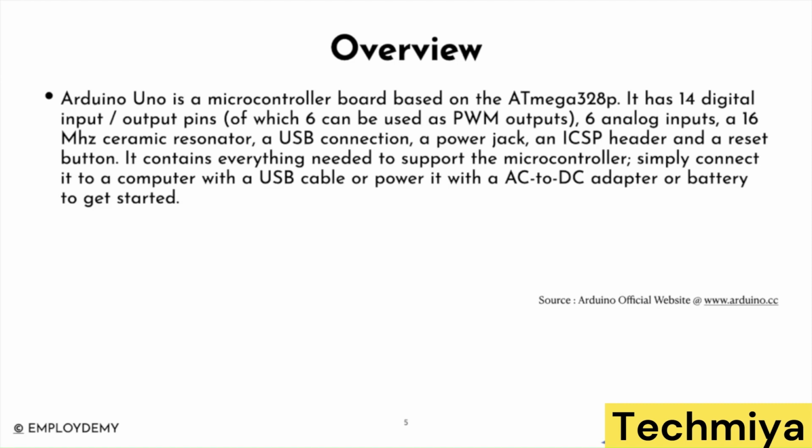255 being the highest, 5 volt, and 0 being the least, 0 volt. And this Arduino board has 6 analog pins. Analog pins, as the word says, are continuous, so the value may change. The value changes from 0 to 1023.